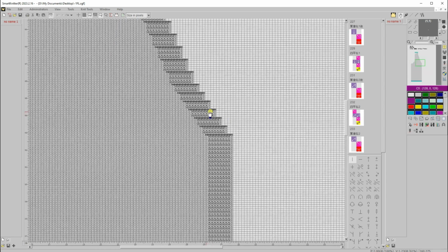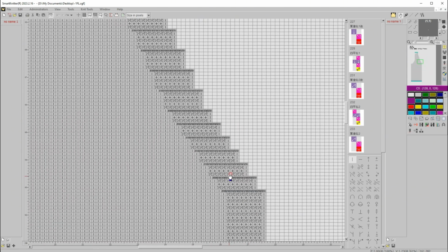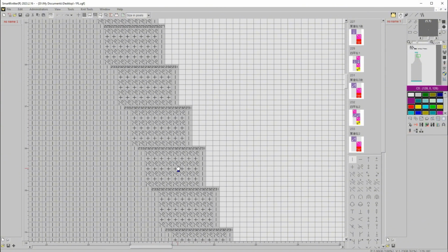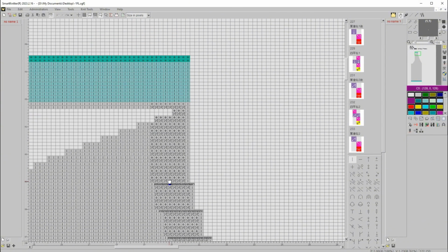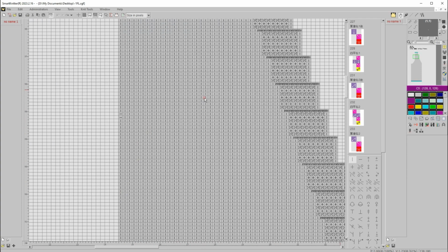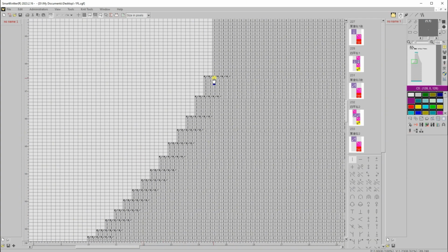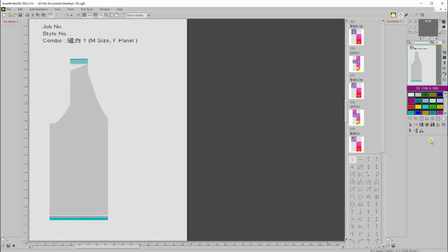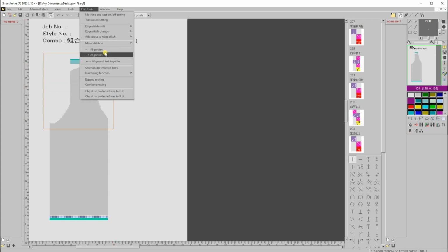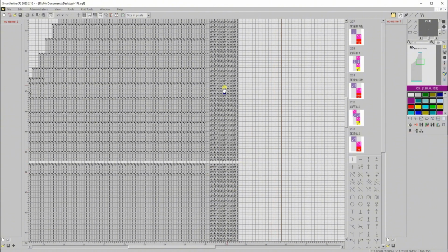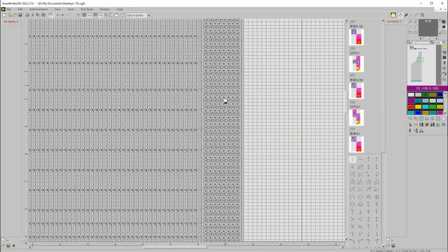Tool 6. Align Trim. This is a cardigan front panel where the trim is half Milano. We could reduce the knitting time by aligning the trim to the right, so that the half Milano trim is knitted in a straight line. Select the area where we want to perform Align Trim. Go to Knit Tools, then Align Trim. The trim is now aligned right. Narrowing is now done on the left of the trim instead.